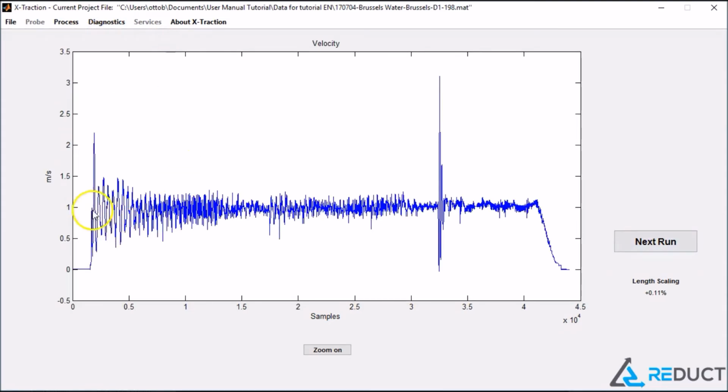The velocity chart shows that the probe traveled at about 1 meter per second. The erratic pattern indicates the probe passing a heavy weld. RPA stands for roll, pitch, and azimuth. Roll refers to the probe rolling around its own length axis. Pitch, or inclination, refers to change in the vertical angle. And azimuth refers to changes in the angle to true north.